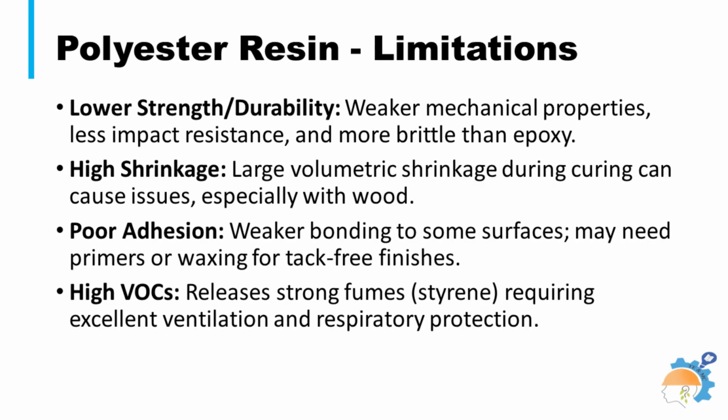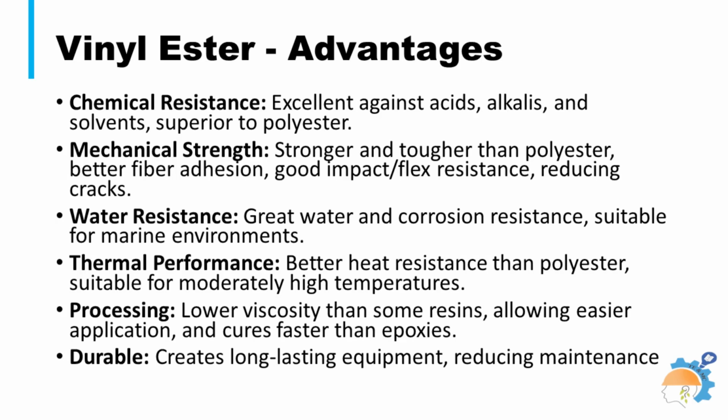Its limitations include brittleness, lower strength than epoxy, significant shrinkage, poor adhesion to some materials, and strong VOCs during curing, making it less ideal for high-performance or intricate applications needing superior bonding or flexibility. These find use in hand layup, resin transfer molding, RTM, pultrusion, and vacuum infusion.